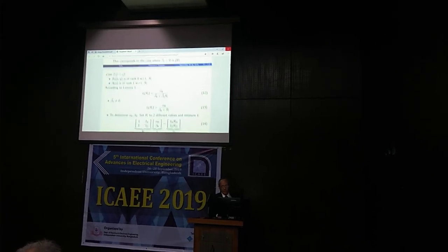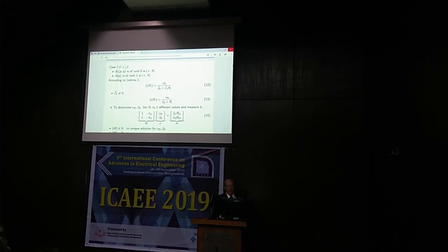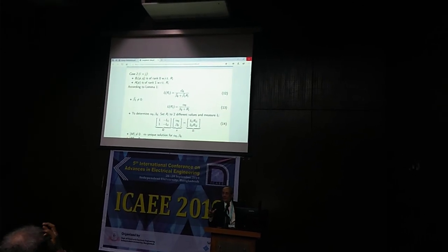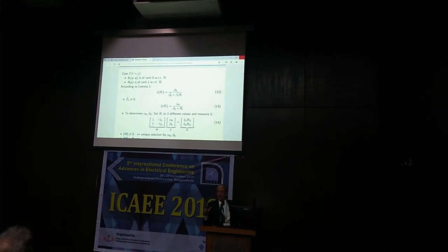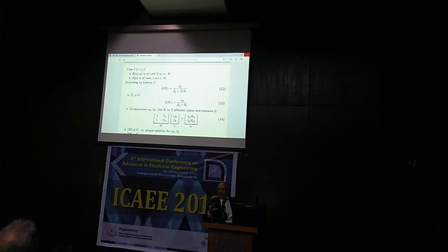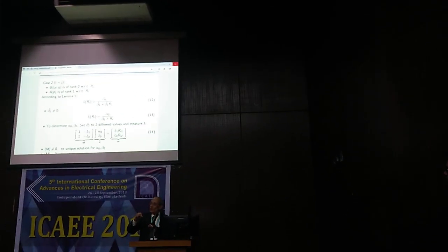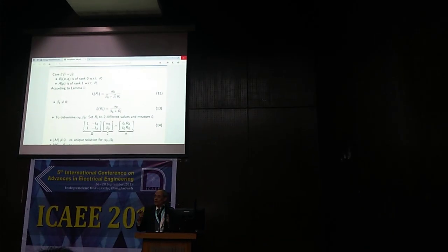And so, okay, it turns out that Thevenin's problem, since we are running out of time, we are going to have to do some homework. Thevenin's problem is a special case of this. It's a 2-parameter problem. And what do we do in Thevenin's theorem? We measure the open circuit voltage and the short circuit current. Well, you don't have to measure those.